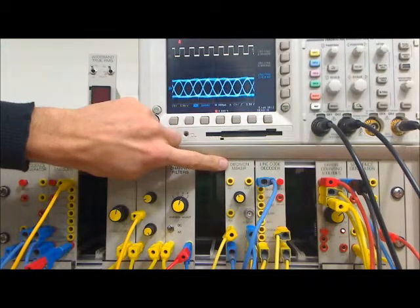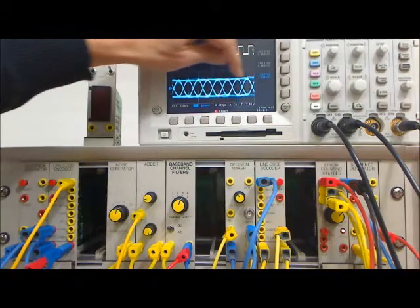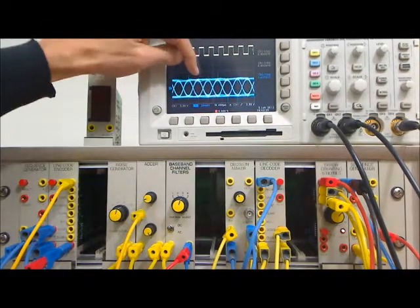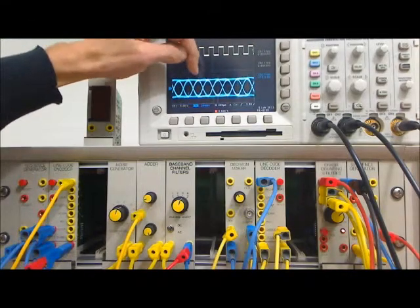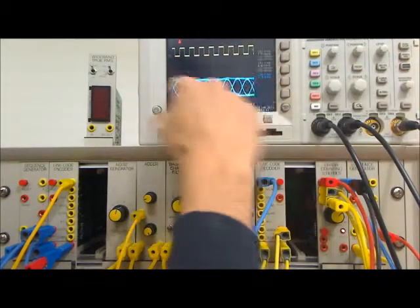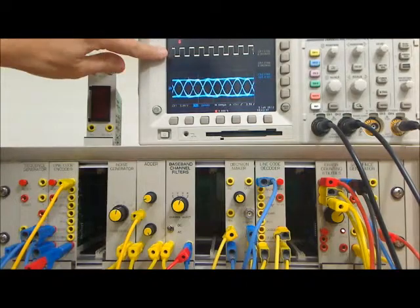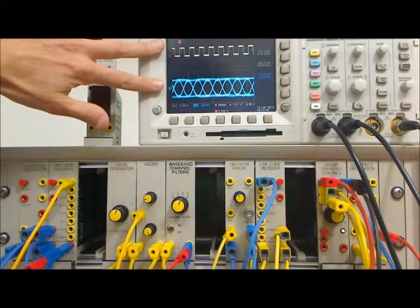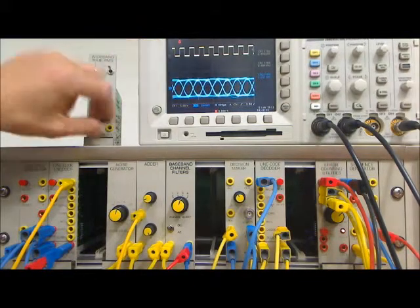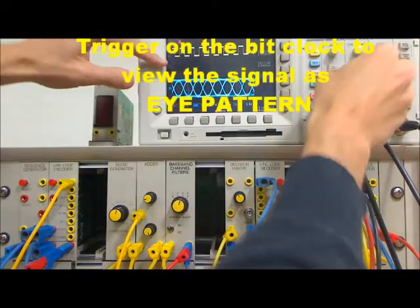The decision maker is the front end of the receiver, and its purpose is to sample the received signal at the correct instant so as to be able to make decisions as to what the level of the signal is at that instant. Because we're triggering our scope on the bit clock, we can easily view the eye pattern at the receiver. I'm just using 2 channels of this 4-channel scope to emulate a 2-channel scope.